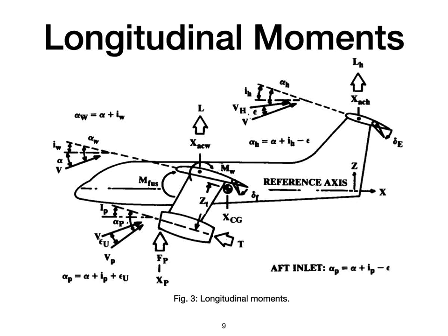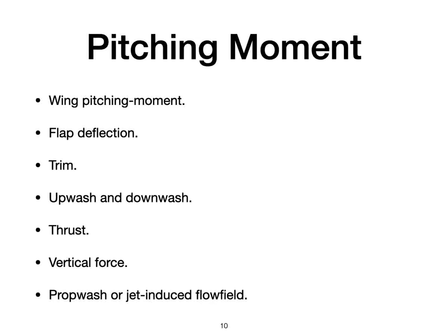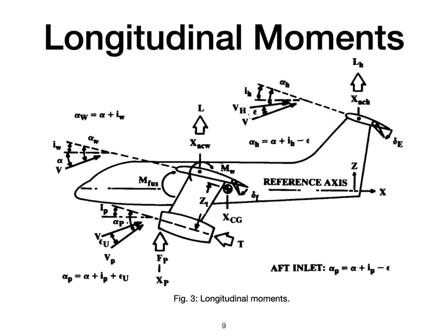Flap deflection also influences the wing lift, adding to that term. Flap deflection has a large effect upon downwash at the tail. The long moment arm of the tail times its lift produces a very large moment that is used to trim and control the aircraft. While this figure shows tail lift upward, under many conditions the tail lift will be downward to counteract the wing pitching moment.